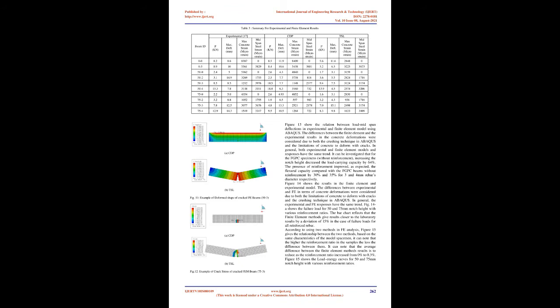[22] Flexural steel reinforcement. For the discrete model, a three-dimensional element is used to model the flexural steel reinforcement. Two nodes are required for this element. Each node has 3 degrees of freedom, translations in the x, y, and z directions. The element is also capable of plastic deformation.